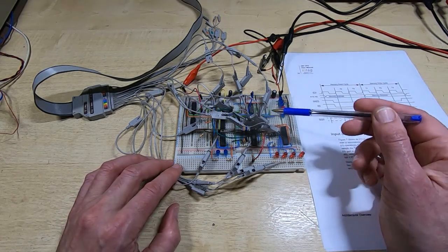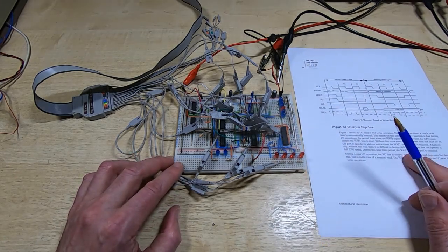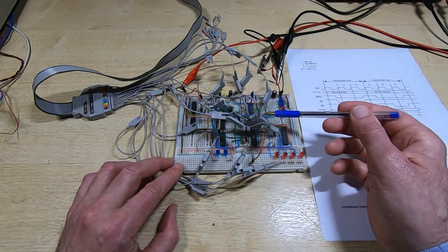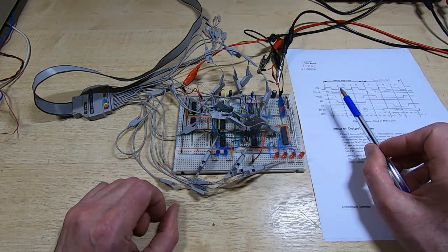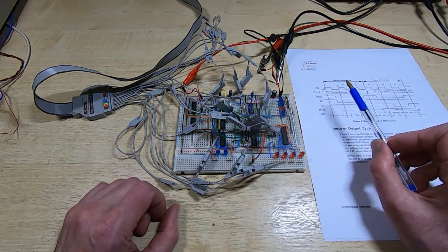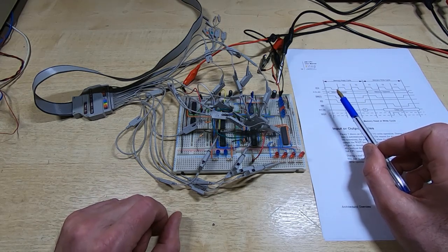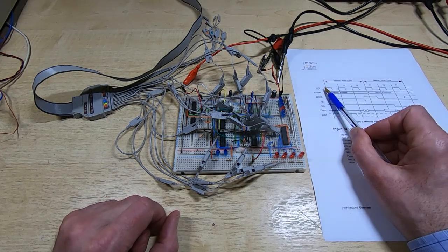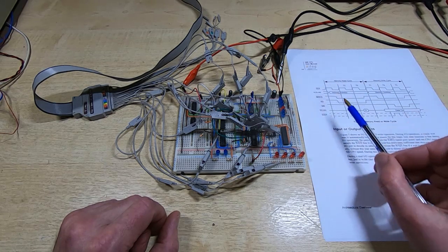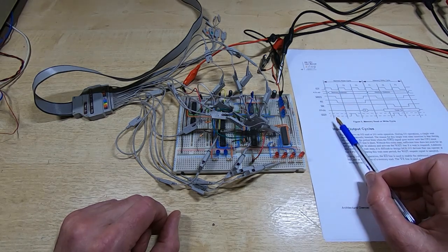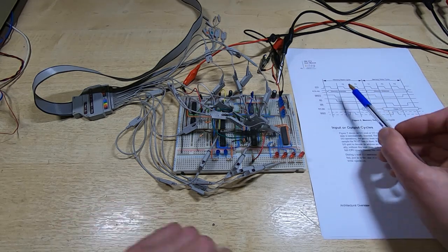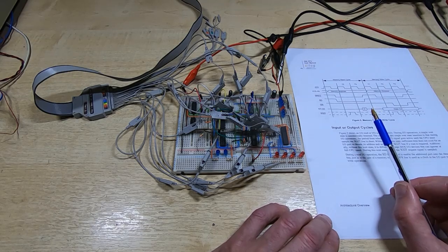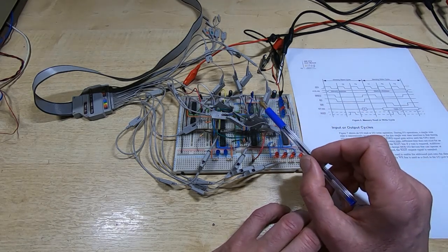So the way we go about this, and I'll show us the circuit in our future video when we look more closely at the floppy drive interface, but the heart of this circuit is a series of 4 daisy-chained flip-flops, and they are fed from the main Z80 clock. So what will happen is when we feed the clock into the first flip-flop, assuming they're all reset into a common starting phase or point, then the signal will ripple through the 4 flip-flops,